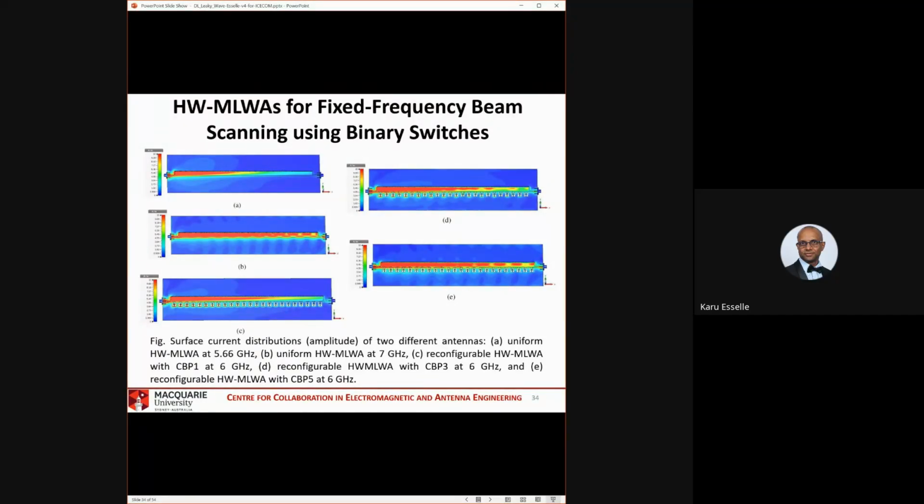We've got two ports, and yes, now it behaves like a standard two-port device. If you look at S21, from port 1 to port 2, it is not insignificant in this case. Here it's negligible, here it is not negligible.